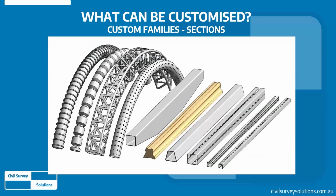Okay, the next type, this is the second layer, I'll say, which is custom family. Now, there could be a lot of possibilities over here. One of the many examples I have shown over here, this could be a beam, this could be a column, any kind of section it could be. So different styles, different kinds of surface patterns. Some are tapered, some are trapezoidal, plus slotted. Many different styles you can create. There is basically no limit for custom families.